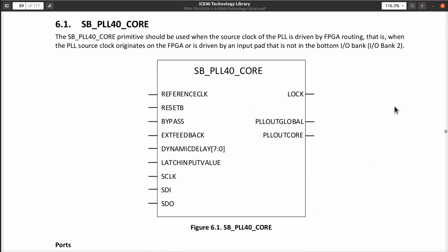in this case, the two PLLs. So it shows you these are the signals that you care about when you configure a PLL to operate as a core module. And basically what you've got is your reference input clock. You got this lock output to let you know if it's okay or not. Is it running correctly? And then you've got these two outputs, which, be careful how you hear that word too, okay? This is one output that can be connected to one of those global buffers, or you can take that one output and connect it to core logic, just regular old routing logic inside the FPGA.